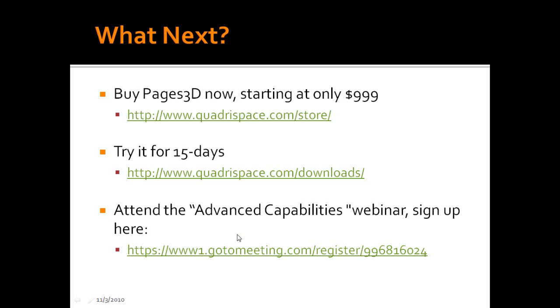And what about CATIA native files? I answered that earlier. CATIA is imported. We don't support CATIA native. You can import STEP files generated from the CATIA save as. CATIA save as STEP will generate some files, and we have customers that use the software in that way. Again, another file format we definitely have on our radar. We just have not done it yet.